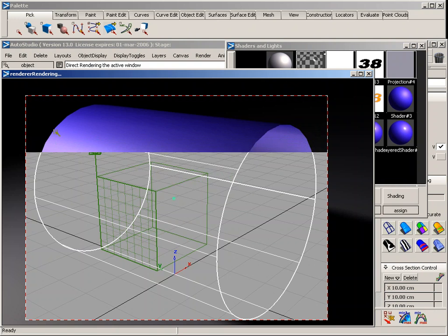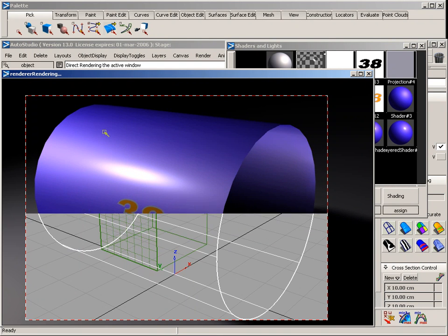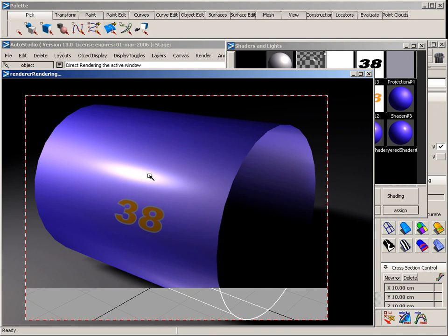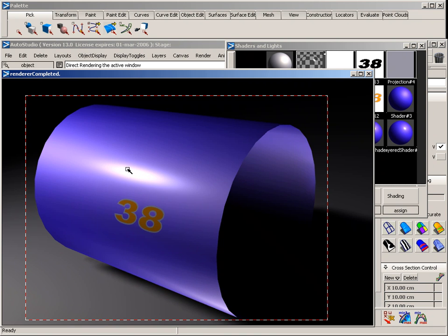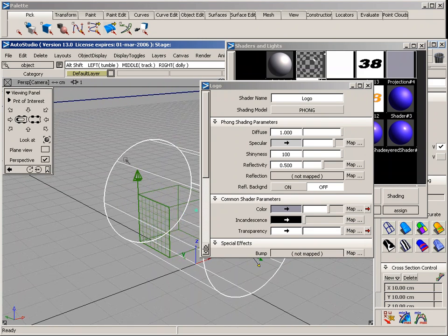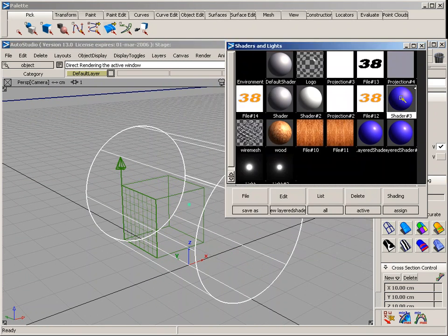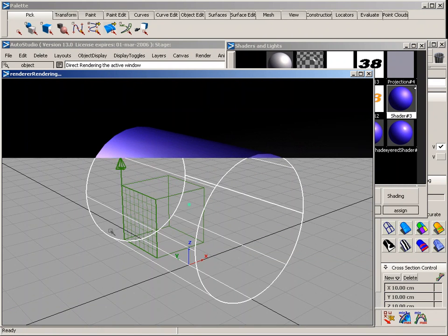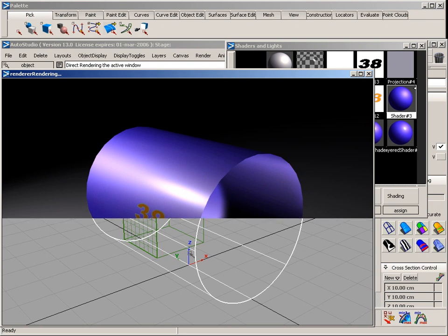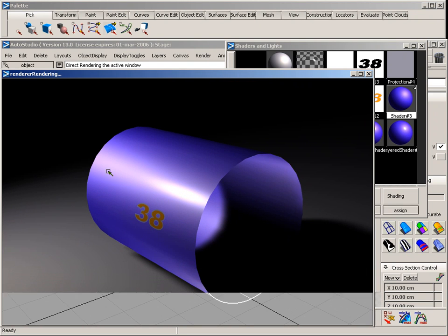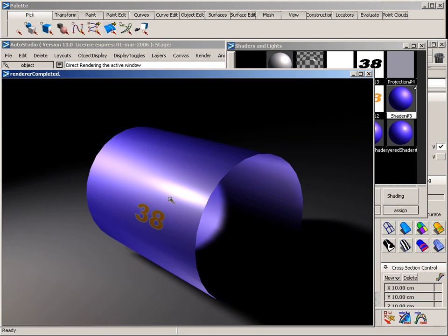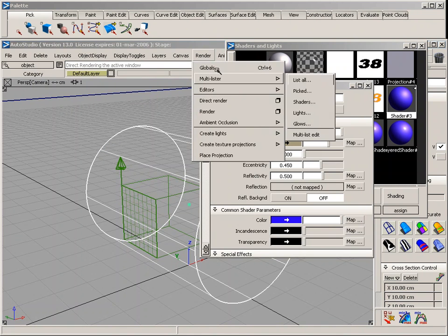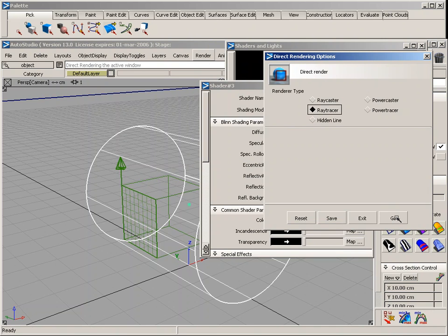What you will get is the Blinn shader creating still some of the highlight area, while the Phong creates this very sharp highlight. Depending on the angle of view that you have towards your surface, I'll go ahead in here, make this a little bit brighter. You could get very strong car paint looking effects. Again, there's the highlight from the Blinn shader and this sort of very sharp, smaller highlight from the Phong. This becomes especially dominant or apparent once you start ray tracing.